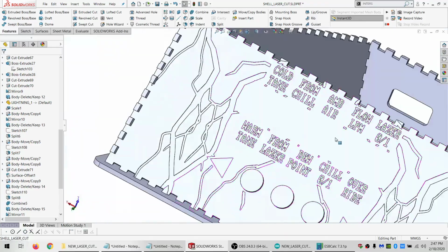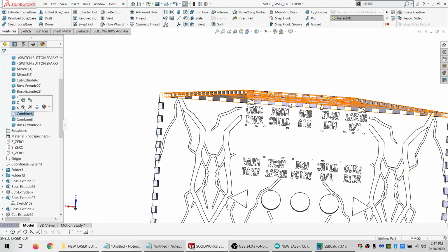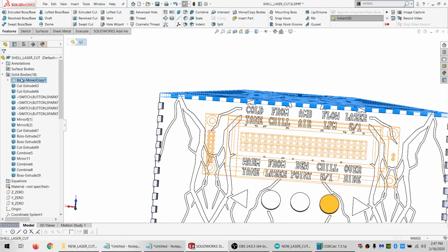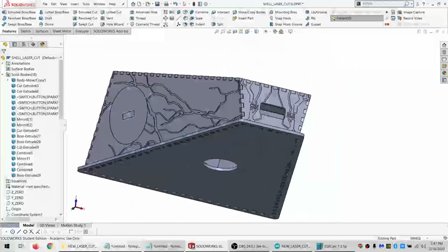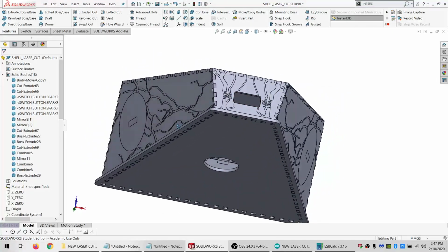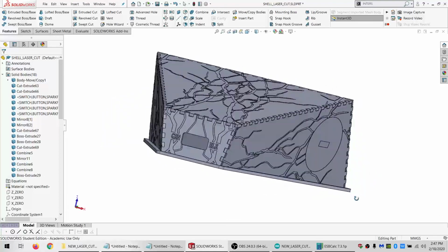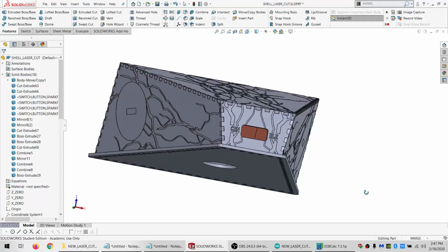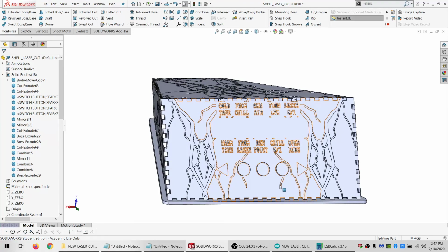And I know that looks kind of silly, but like I said, it's translucent, so it'll shine right through. All right, so that is, as far as I can tell, design done. And neat little shape if I do say so myself. So, I'm gonna add the kerf, do a flat layout with it, and then it's ready to burn.